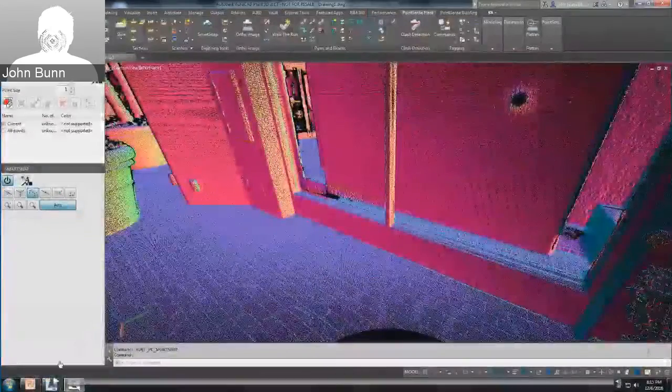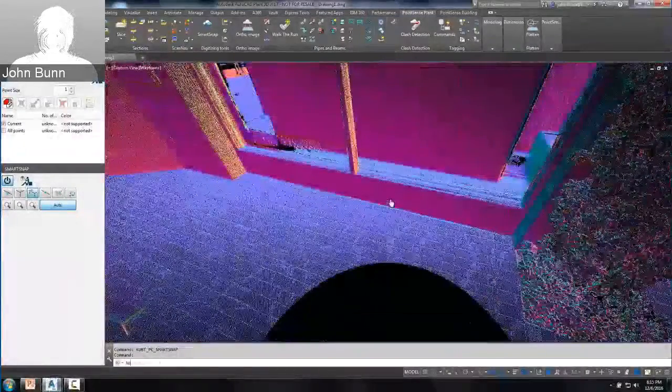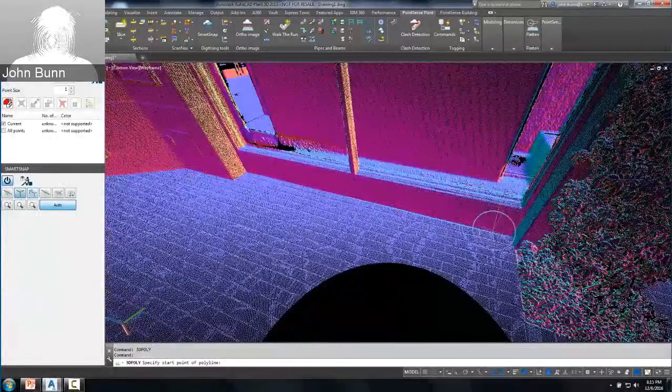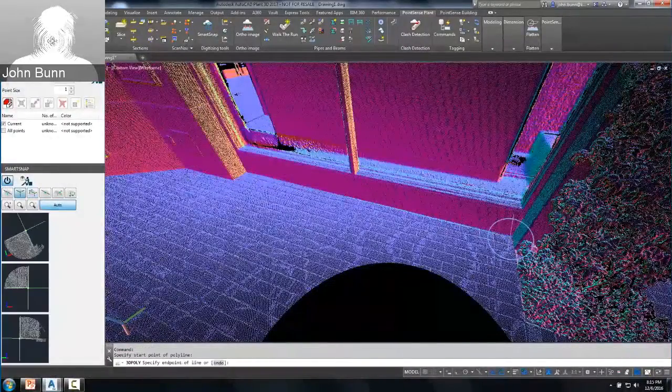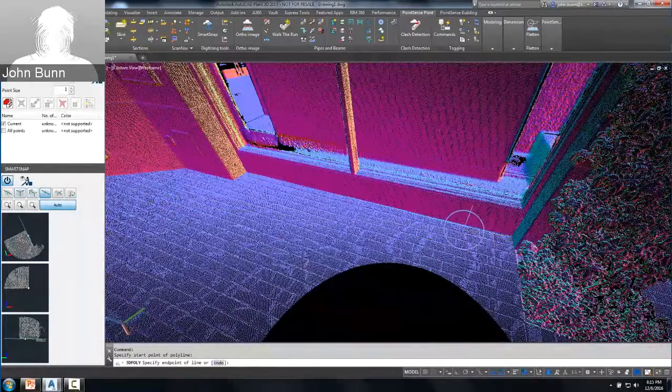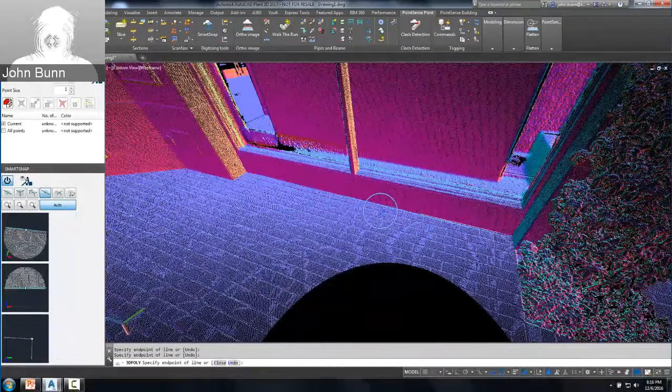In this example here, I turned it to a normalized color mode. It just makes the faces easier to see. You can see my smart snap on the left there. You have an option for corner point. You also have an option for corner or edge if you want, but if you notice, as I'm clicking points, my cursor is not on the edge. Like I said before, the edge just needs to be within that search region.